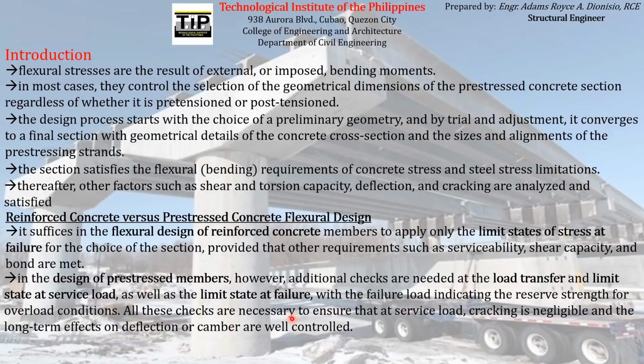If the tensile stress acting on the concrete exceeds the strength of the concrete in resisting tensile stresses, the result will be cracks, and any cracks produced in a concrete element tend to propagate gradually along the concrete itself, which may result in total failure of the concrete element itself. So we don't want that scenario to happen.